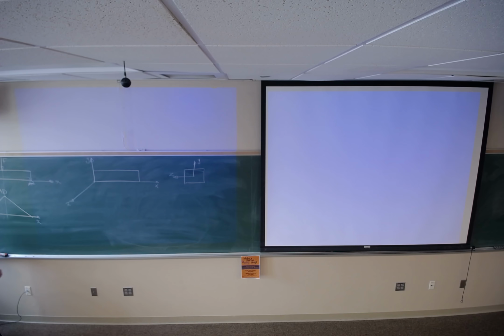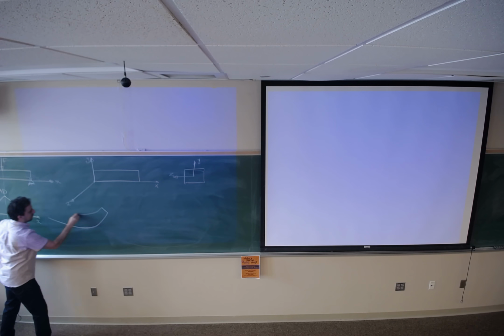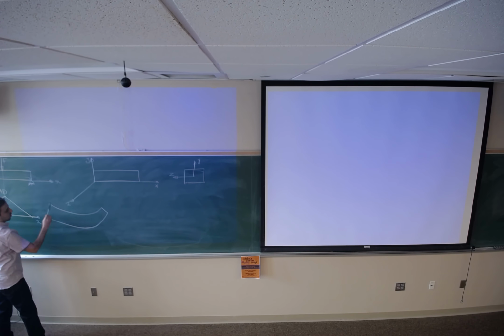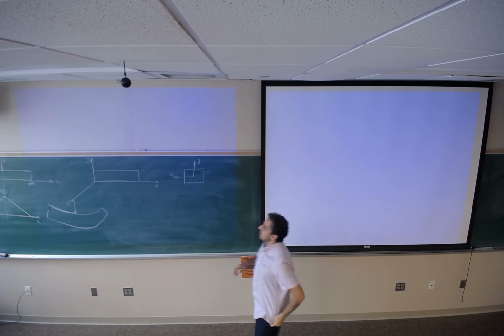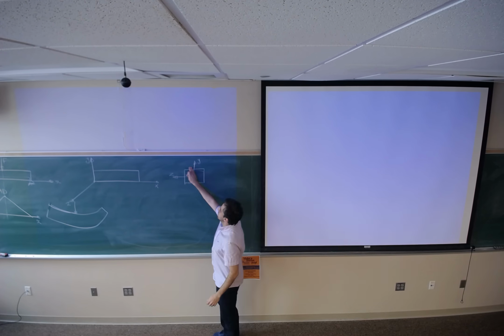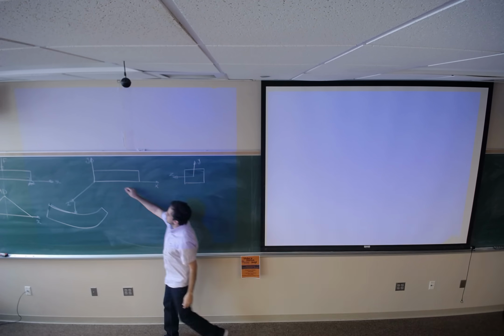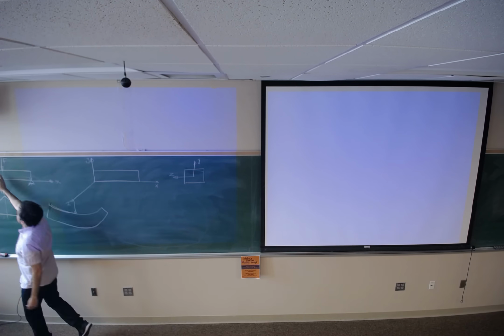Now, the question that we should answer is, if this beam is under this loading, on the extreme side it's going to bend like this. So due to this loading, you will see bending something like this on the beam. Now the question is, what kind of stress is this bending moment going to create in this section, which is the critical section of the beam?